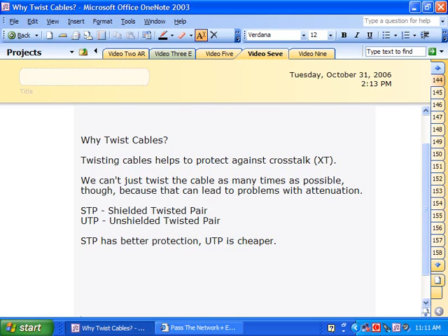because that's usually the way you see it expressed in documentation. Now, twisting the cables, or twisting the wires inside the cable, actually helps to reduce the impact of crosstalk on the signal that the wires are carrying. And this benefit increases as the wires are twisted around each other more and more. It prevents another data signal or another kind of electronic signal from coming in and impeding the ability of these wires that are now being twisted to carry the data to begin with.